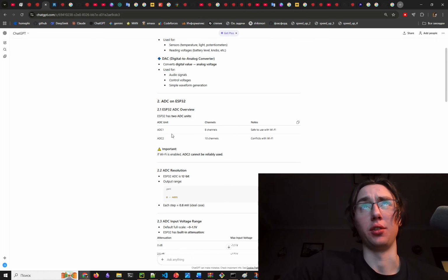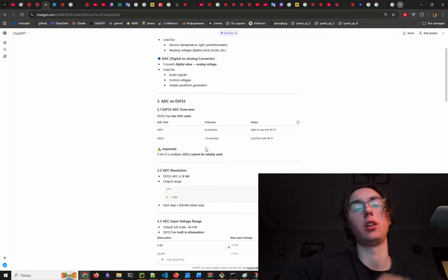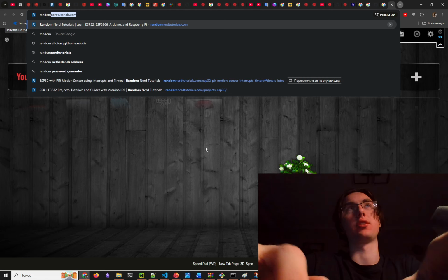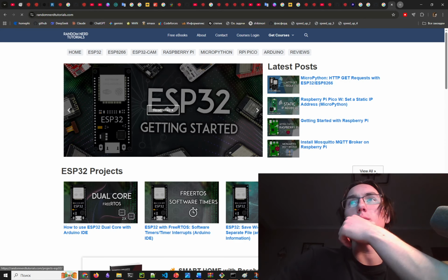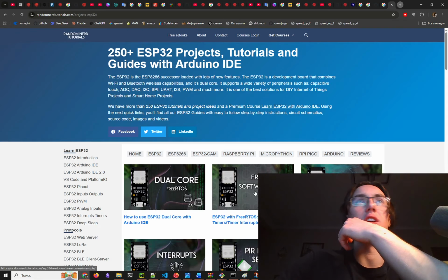ESP32 has two ADC units: ADC1 with 8 channels and ADC2 with 10 channels. I saw that on a Random Nerd Tutorials article where there were pinouts of the ESP32.